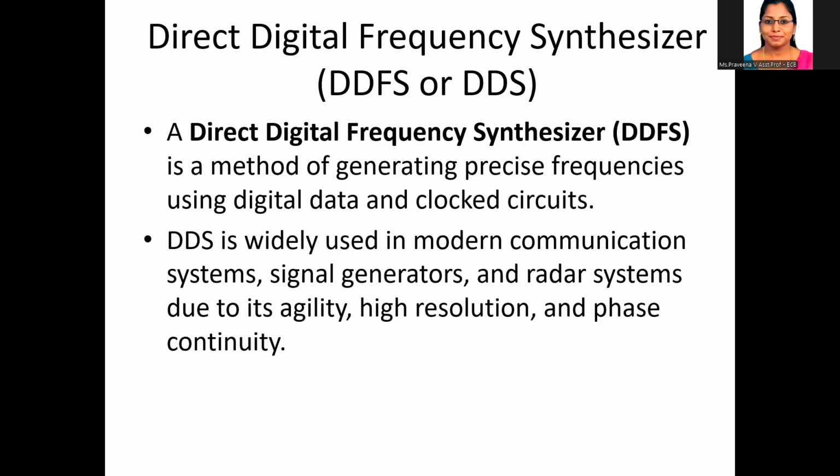Then we are going to see about the direct digital frequency synthesizer. DDFS is a direct digital frequency synthesizer. It is also known as DDS, the direct digital synthesis. It is a technique used to generate precise and programmable frequencies using digital circuits and a reference clock.